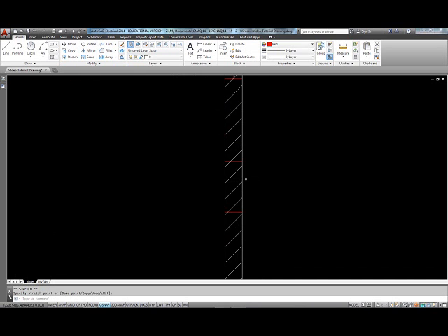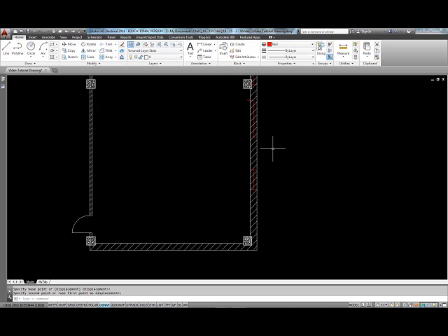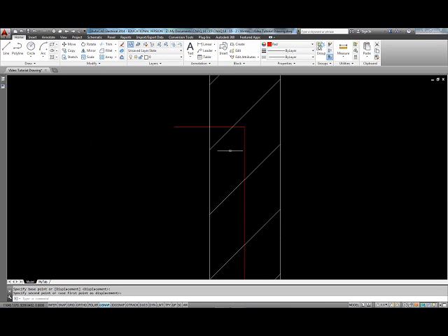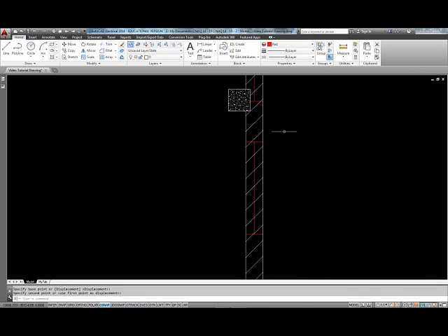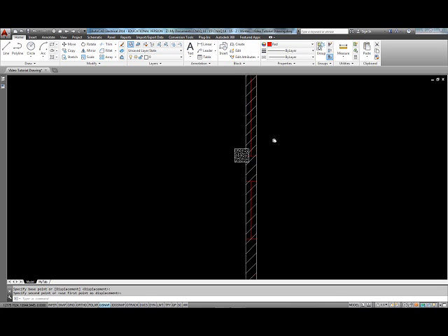Let's go down further. I have a line there, and then move it from either the top or the bottom to the middle. And now, what happened here? Let's see. Oh, it actually moved. I didn't move it. I should have extended it. So now I should move it again. Move from this point to the perpendicular. Okay. Now let's do some trimming.